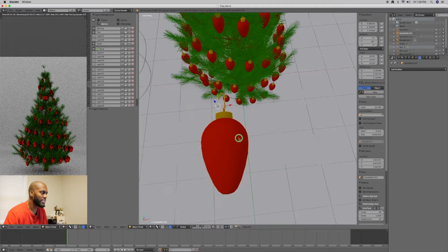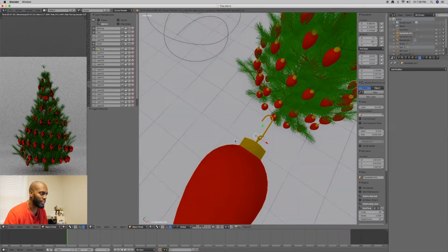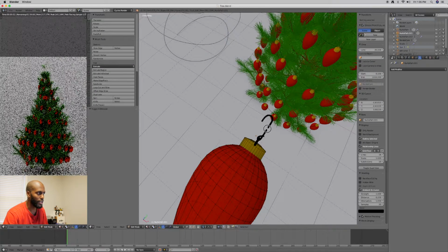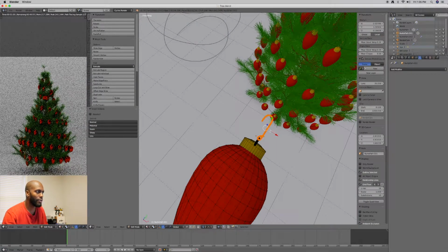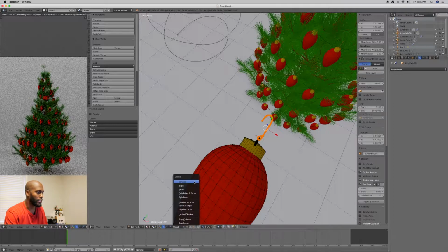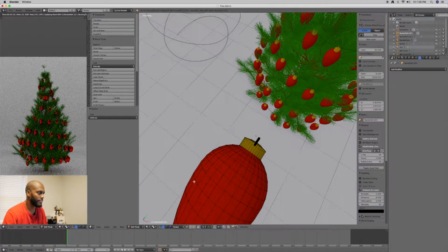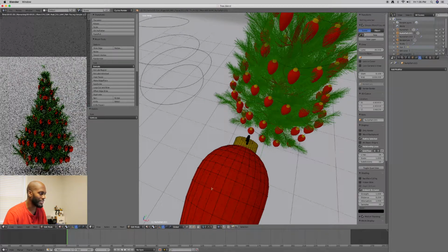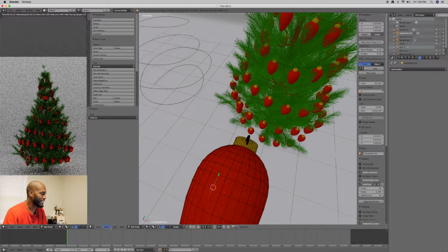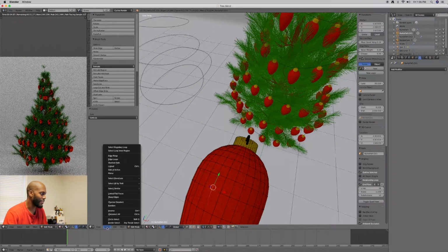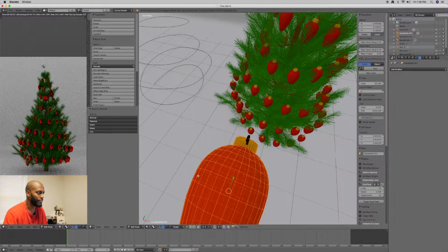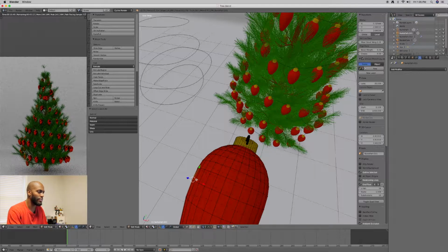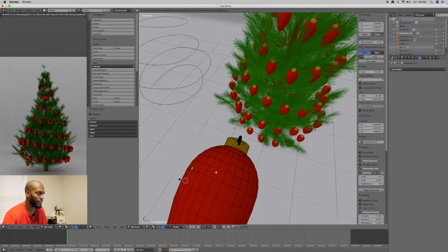One thing that we don't see on lights is the hook. So let's go ahead and get rid of the hook for now. We're gonna grab the hook, push L, then push delete vertices, and that'll get rid of the hook. When I pushed L, what's happening is you can either go to the select icon right here and it'll be linked, or Control L for that, and it'll select everything linked to that, or you can push L and it will do the same exact thing.